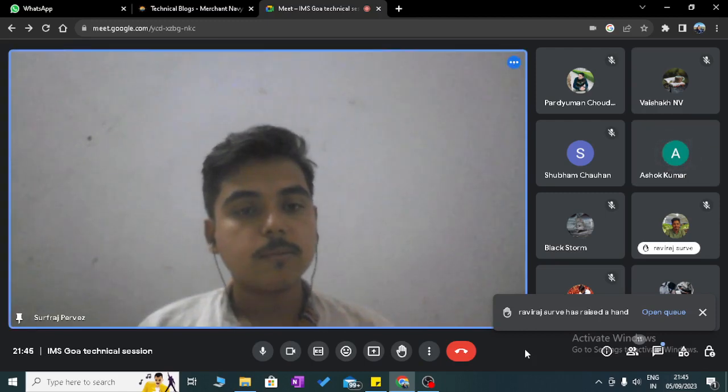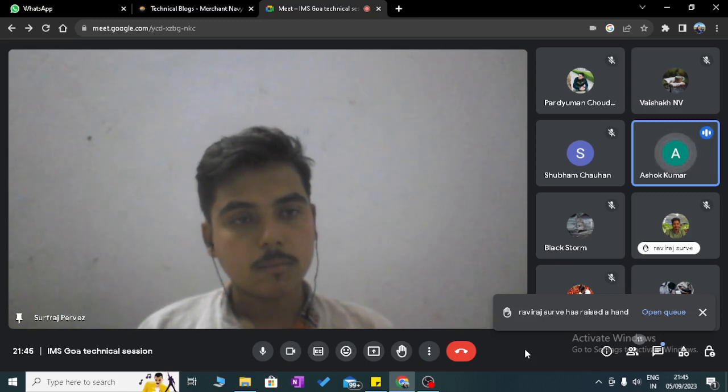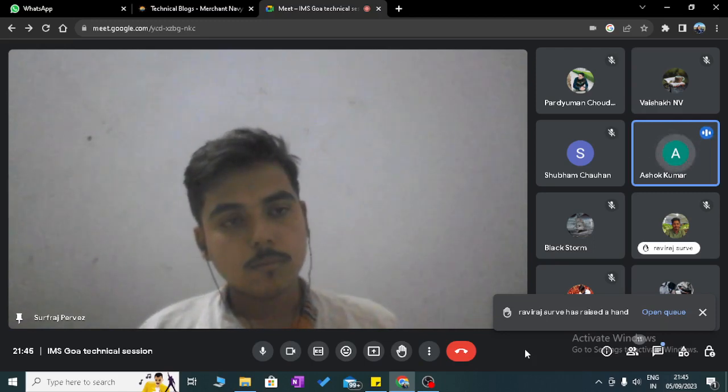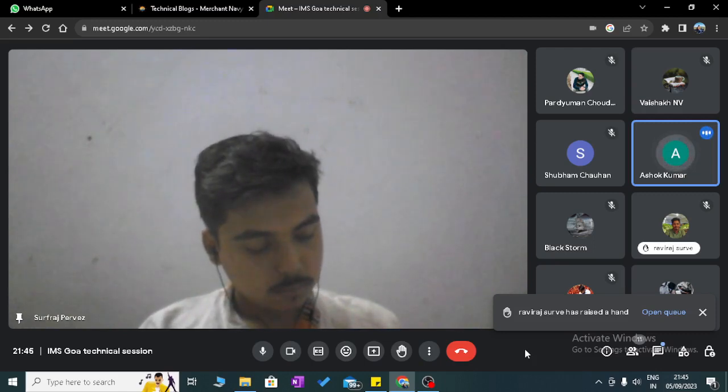Net, there is a suction pressure, which means a low pressure side. If the liquid turns into vapor at a low pressure side, which means the pressure at which liquid will turn to vapor, so vapor goes into the pump. It will create a bubble, an air bubble. So it will go from the low pressure side to the high pressure side, and it will implode.